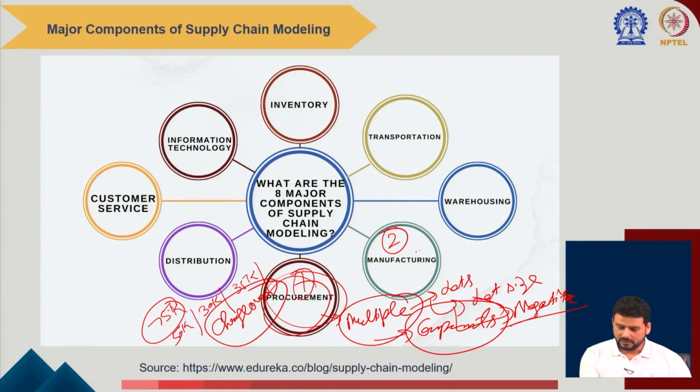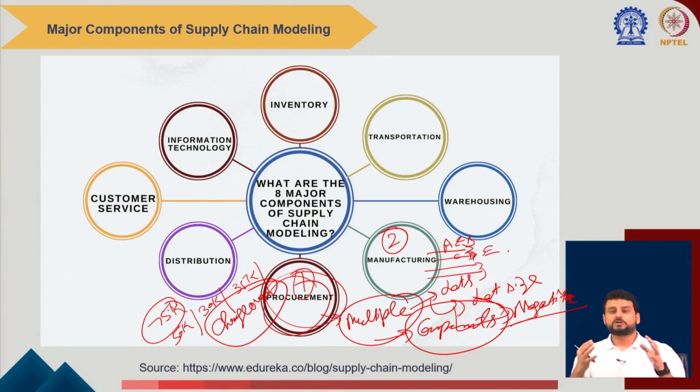So, then how much of one particular model you will produce, if you are having 4 or 5 different production lines, this is producing A and B model, here we are producing C, D and E model. So when you will go for changeover, right? So that optimal level you can decide that if I will run this particular production line for 10 hours continuously, that much is going to be the productivity, because whenever we are going for changeover in the process, initial time we are taking to set up, to standardize that, and then we can produce some rejection as well. So those factors we will consider.